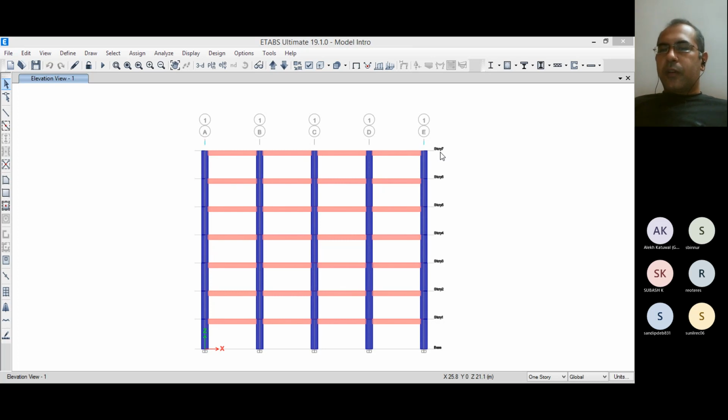Okay, because the solution is in matrix form for dynamic analysis. Okay, for static analysis, it will be just calculation of the weight at each of the story. For dynamic analysis, you have to create the matrix. So we will create a mass matrix. Okay, we will see it later. Just remember right now. So at each story, you calculate the mass. For static analysis, use those mass as a weight. And for dynamic analysis, create a mass matrix. That is how we do it. So for response spectrum method, you will have to create a mass matrix.